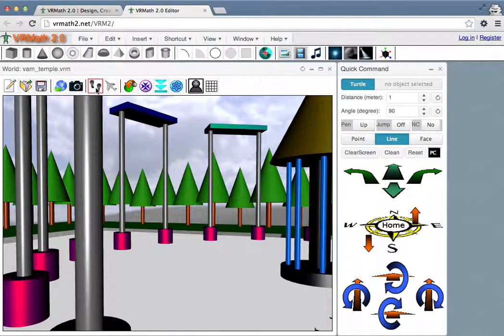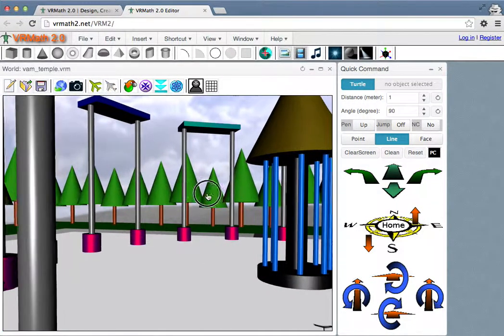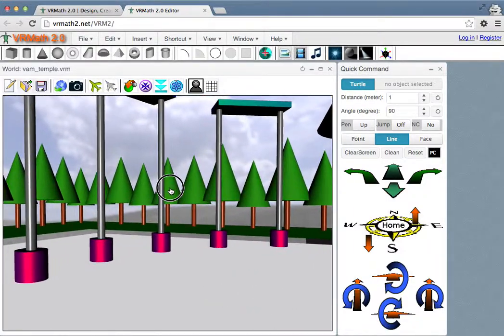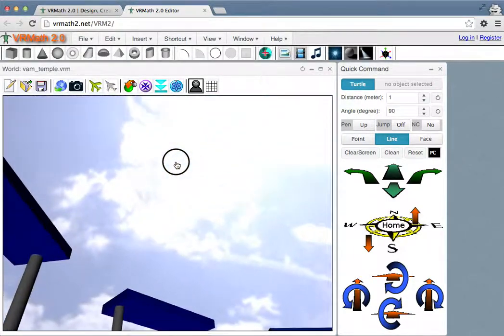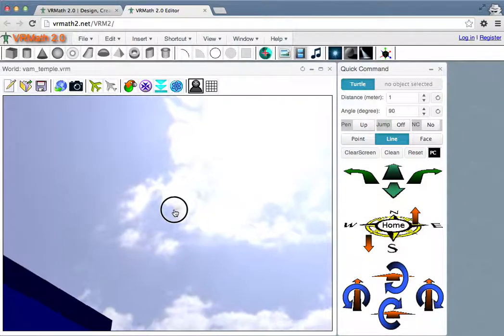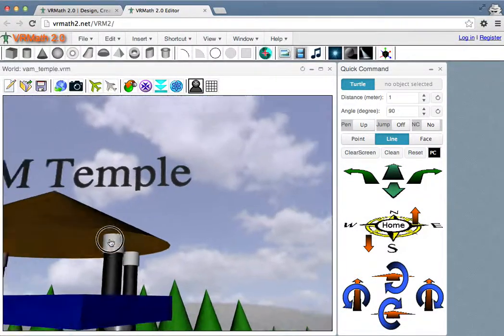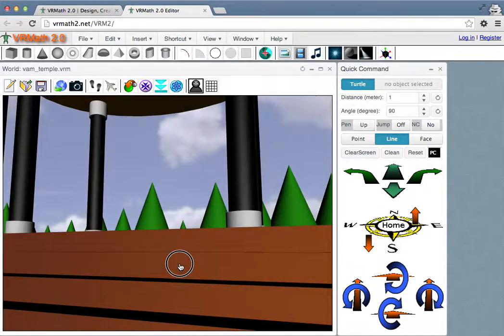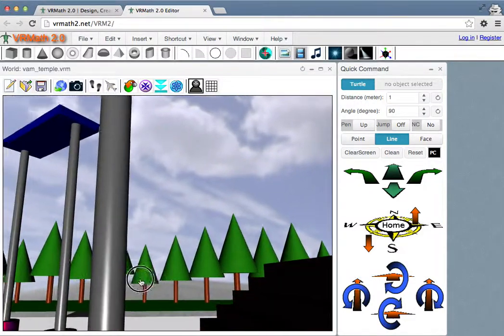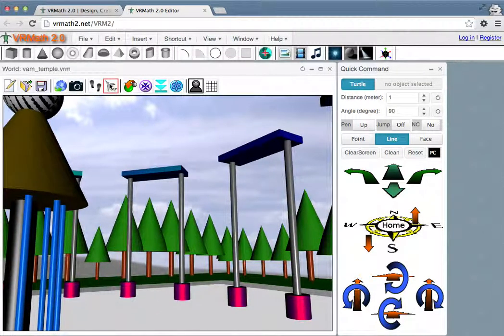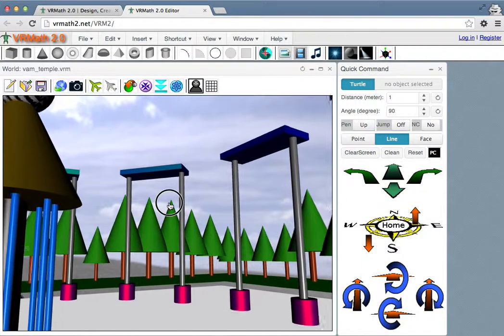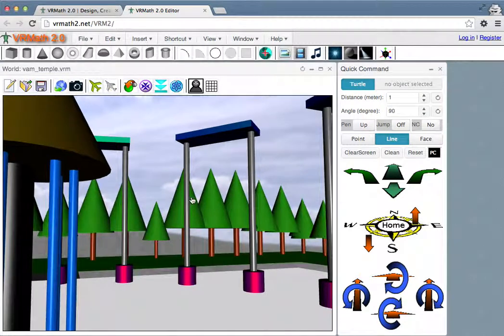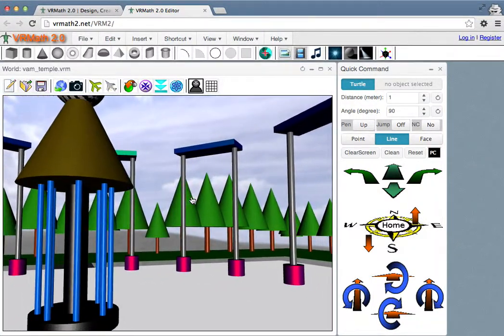If you change to fly mode, it allows you to look up and actually fly into the space. That is the different thing. If you use the walk mode, it's impossible to fly. It will drop down to the floor immediately. And same thing in the fly mode: the left click is to fly forward, and the right click is to fly backward.